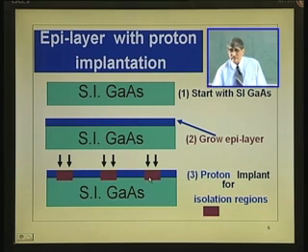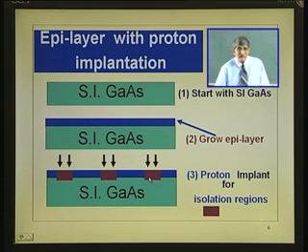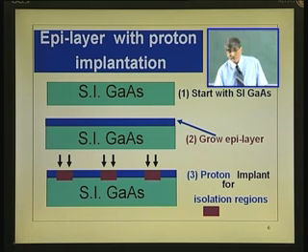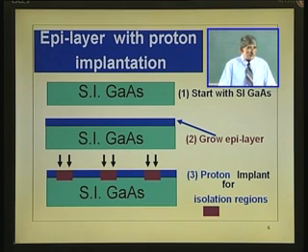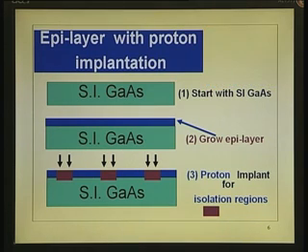Do not think of annealing it now. If you anneal it, you have to go to a much higher temperature, then you have to recover and the epi layer will come back. So, do not anneal it, bombard it. Low temperature annealing will not do much. Okay, so these are the three different approaches used.